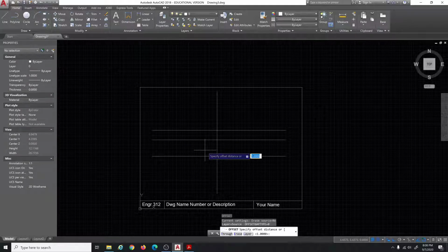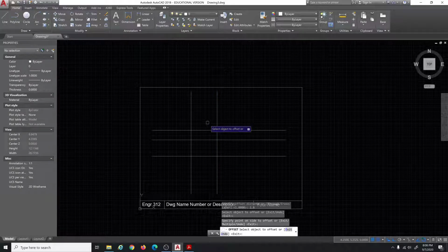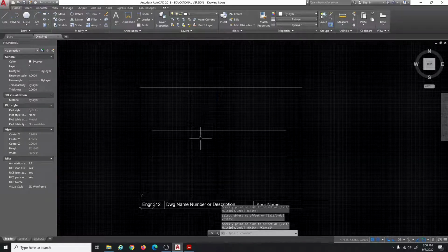Then 1.6 over to the side. That's half of 3.2. The 3.2 is all the way across. If you look carefully on the dimension drawing, there's only one arrowhead. So they really mean all the way across. But we're using half of that because we're just drawing from the center line over. We're just drawing half the part at one time.